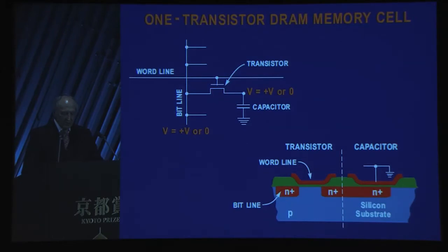To preserve the data, it must be refreshed by reading it out and writing it back into each cell at certain intervals. Fortunately, the speed of this memory scheme allows more than 100 million read or write operations per second, and only a small percentage of these are needed for refreshing the data. Thus, this scheme became known as dynamic RAM, and commonly called DRAM. Next slide.